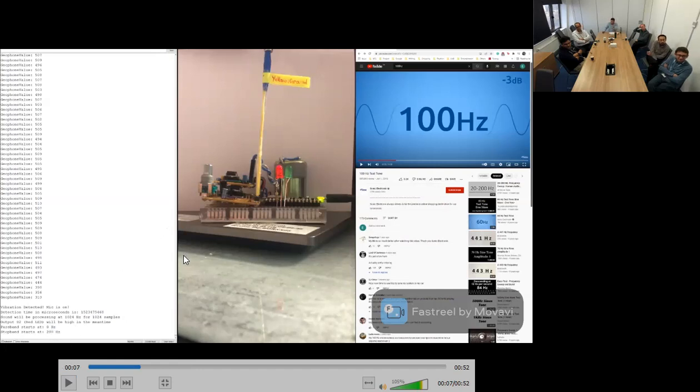And in this setup, we are seeking frequencies from 0 to 200 Hertz, and the capturing time that I set is 3 seconds. So the device listens to the environment for 3 seconds and then reports a power value, which is meaningless here because we can't calibrate the device.